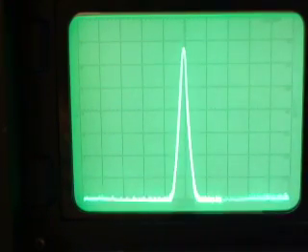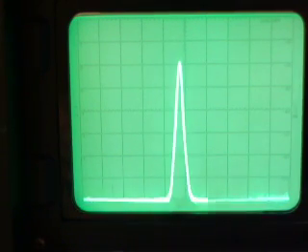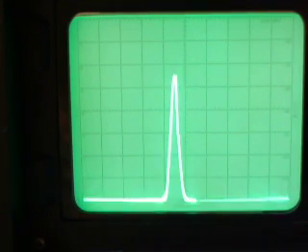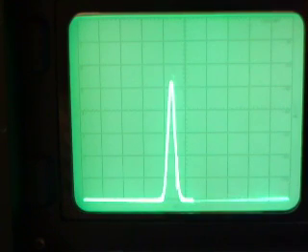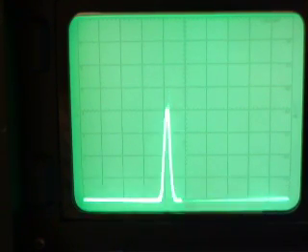So what I'm going to do is I'm going to just start to lower the frequency fairly slowly, and as the frequency drops, you can see it's moving to the left on the spectrum analyzer as you'd expect, but you can already see the characteristics of this crystal filter, because the amplitude of the RF that's getting through is dropping all the time. Now remember that this spectrum analyzer is a logarithmic instrument, so already from where we started at